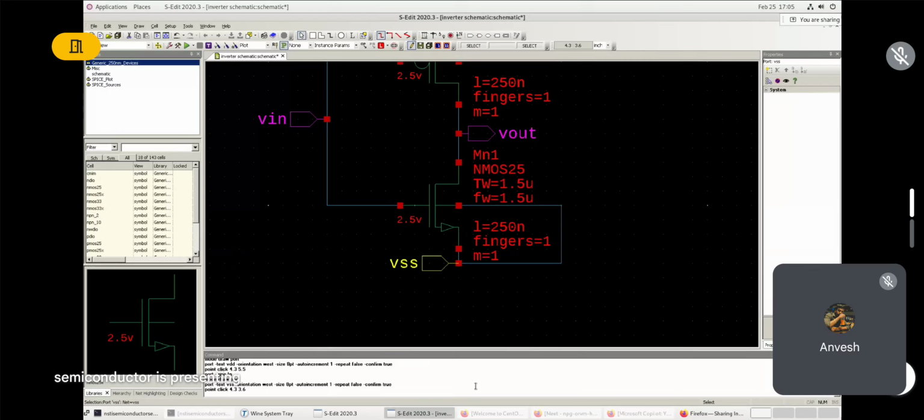Whatever you are giving here, once you get the netlist after completion, you will launch the layout, right? There, you will get the 4 separate columns like VDD, V in, V out. There you have to place the connections inside, like base to source connection, gate to gate connection, drain to drain connection. So this is the base to source connection I am doing. And here its output will be the drain to drain, and gate to gate connection will be the input. Similarly, it will work. These are all basic things. If you know the basics of CMOS, you can make these connections.